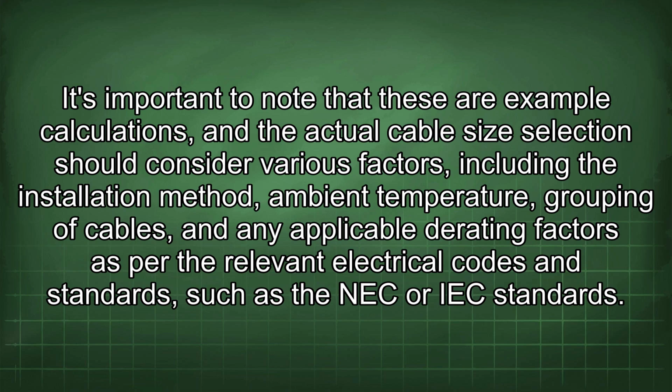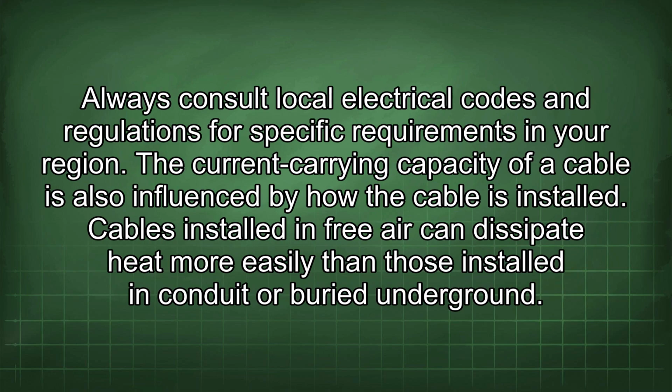It's important to note that these are example calculations, and the actual cable size selection should consider various factors, including the installation method, ambient temperature, grouping of cables, and any applicable derating factors as per the relevant electrical codes and standards, such as the NEC or IEC standards. Always consult local electrical codes and regulations for specific requirements in your region.